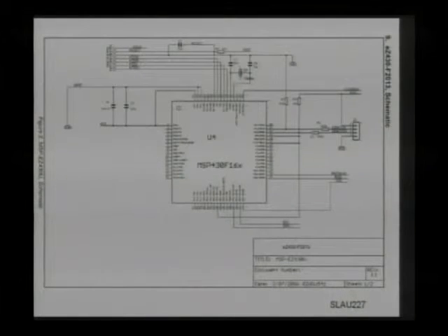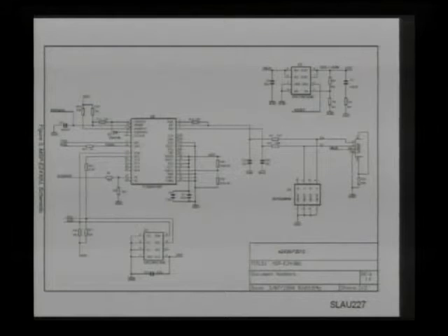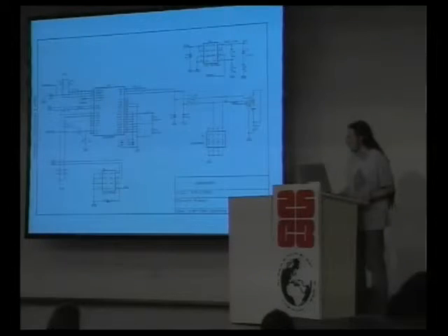So here we have the MSP430 along with the programming port, J2 on the right. You have series resistors and all of that stuff. And then there's a USB to serial chip, the TUSB3410, which is similar to the FTDI chip many of you will be familiar with. And there's a serial EEPROM, the CAT24FC16UI. Sometimes that part number varies. It'll be a larger EEPROM.